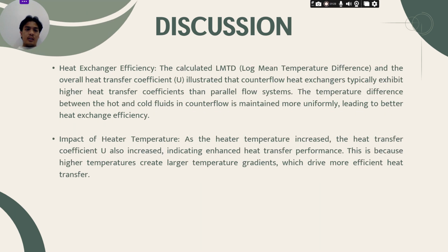The third one is heat exchanger efficiency. The calculated LMTD, or log mean temperature difference, and the overall heat transfer coefficient, which is U, illustrated that counterflow heat exchangers typically exhibit higher heat transfer coefficients than parallel flow systems. The temperature difference between the hot and cold fluids in counterflow is maintained more uniformly, leading to better heat exchange efficiency.